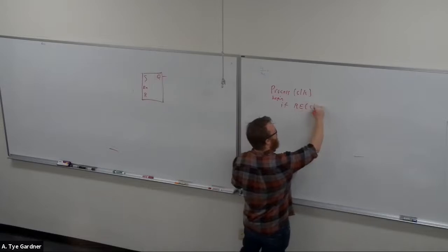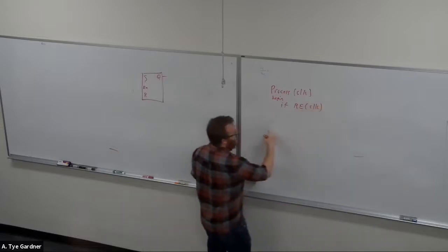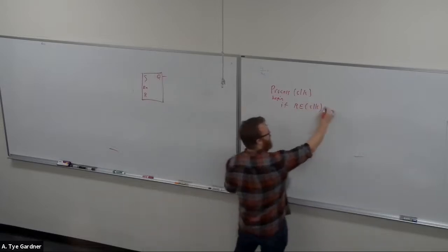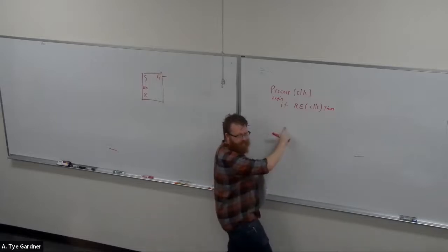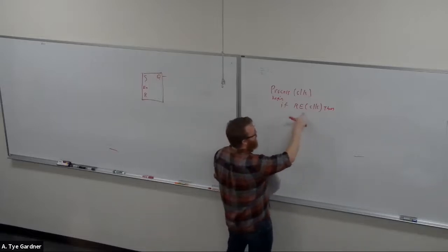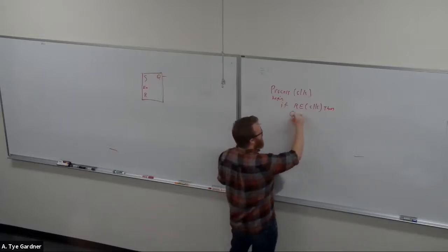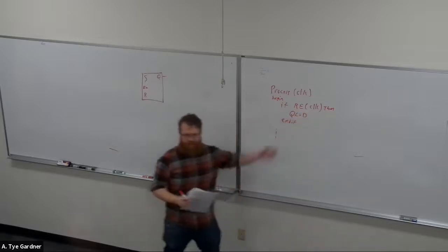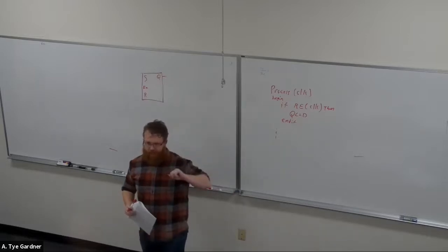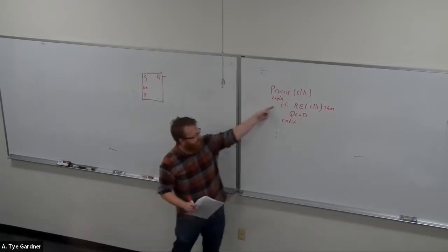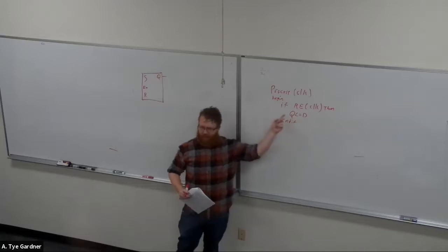If rising edge of clock, then do stuff, right? And so like if it's a D latch, if there's a rising edge of the clock, then Q could get assigned to D. Right? I've made the world's simplest D flip-flop, because I have a clock signal that is taking something called D and putting it on Q.